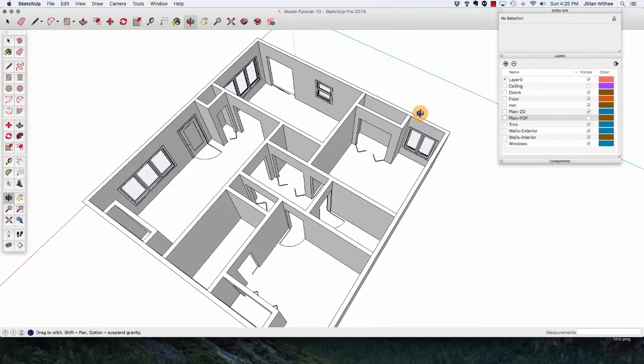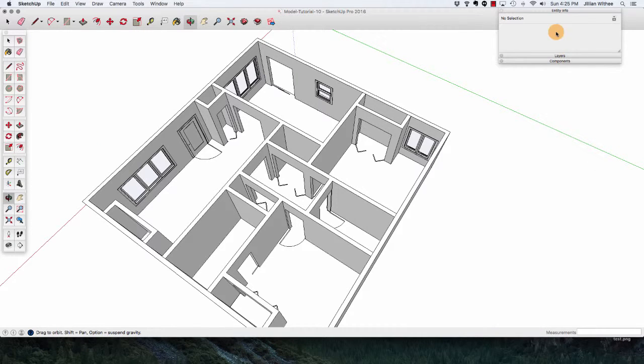Okay, now we're back and we have increased the openings of all our interior doors that are going to receive doors, not these just drywall openings. But all of our bifold doors and interior doors, we have increased them by 1 inch all the way around. So top and sides, so that they're ready to receive their doors. So we are going to start by modifying our exterior door component.